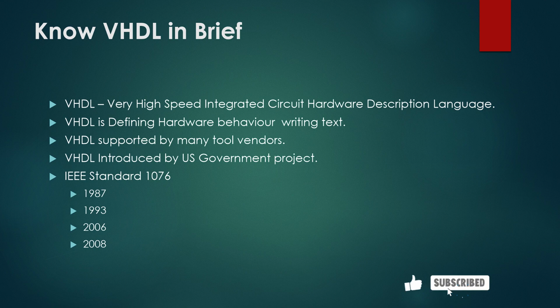So VHDL stands for Very High Speed Integrated Circuit Hardware Description Language. I know it's quite long, but it is. VHDL is for defining hardware. This is a high-level language, which means it is written in text form, and this makes it easy to read and understand, like other programming languages we have. A good thing about VHDL is that there are many tool vendors who support it for simulation and synthesis. That means you have the flexibility to choose.